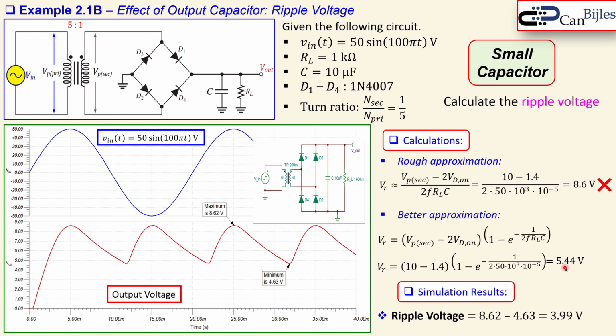So it is 1.45 volts difference between the calculations here from the better approximation and the ripple voltage we have determined from the simulator. Again, the reason is there is some slight error in the voltage drop, because we expected here it was, you can see that 7.6, not 7.6, so you'll have actually 20 millivolts here, but that's not really important.